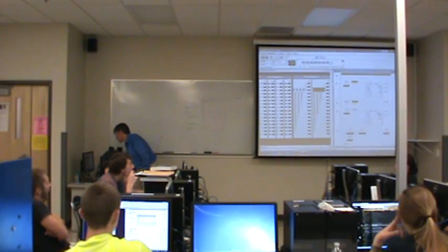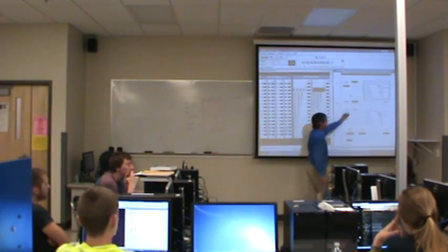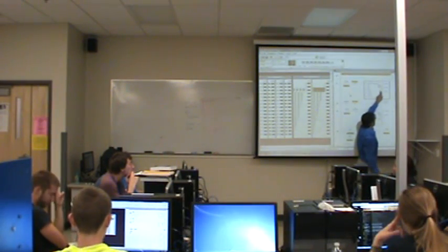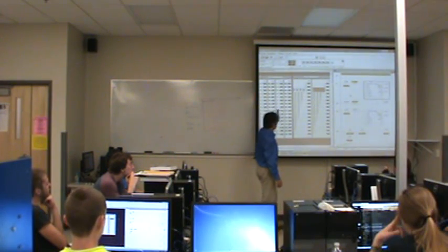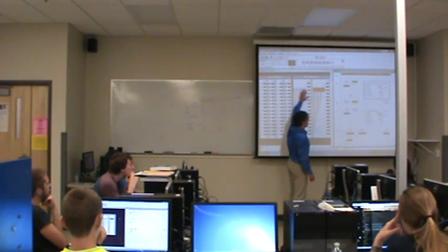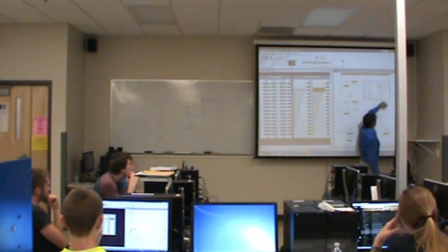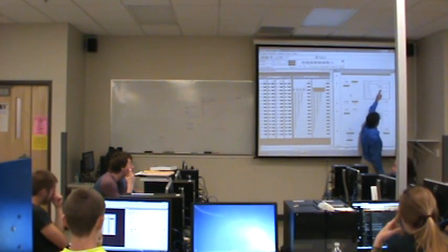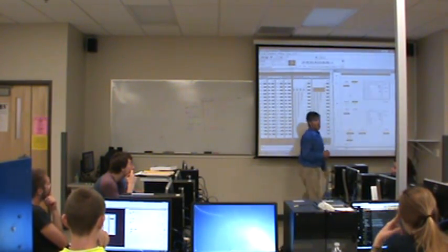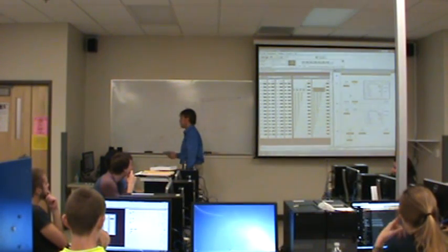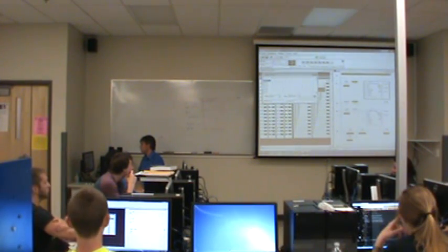Let me describe the sequence compare instruction next, because what this does is kind of the opposite of what this does. This instruction looks at all the inputs on whatever address you tell it to look at. I told it to look at address 5, which is right here. So I'm going to put inputs in here. So it's going to look at all of those inputs, all 16 bits, and what it's going to do is compare the inputs to what I have in memory at this address, but also in a list.